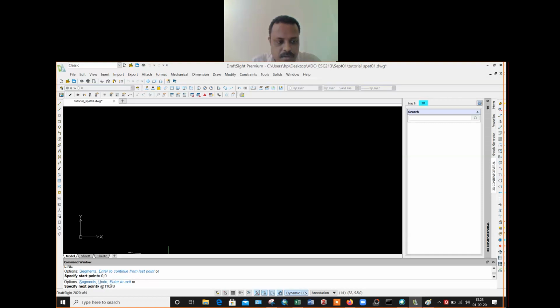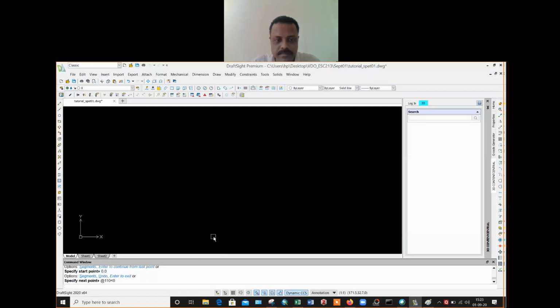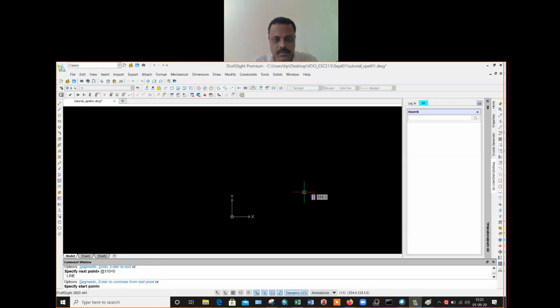How much should I go? 110 millimeter. Please pay attention. Everyone, @110<0. So you write @110<0. That means I am following this line 110 millimeter. Then enter. Where is my line? For that, zoom, extend.